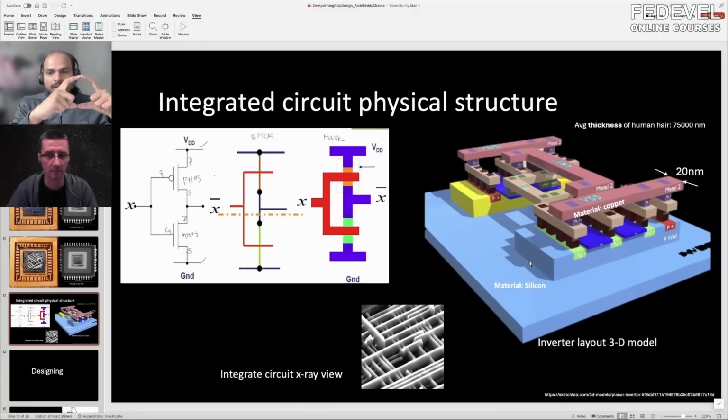I have this big transistor now, but I only need a contact at one particular place. So I put another mask where I have an opening where I want the contact. These are the contacts, the brown ones. Then I cover the rest of it, and then I fill it with material. We have different types of material that we use for these contacts. Cobalt is one option. Now, recently, they are also switching to tungsten because of the electrical properties.